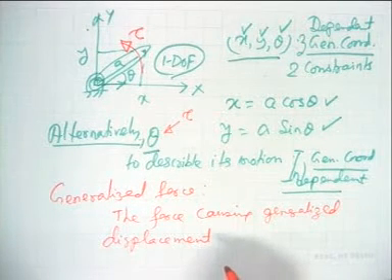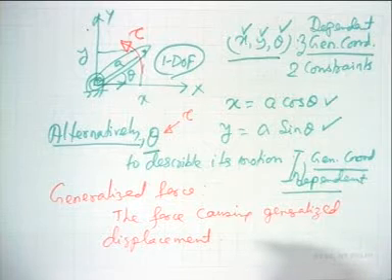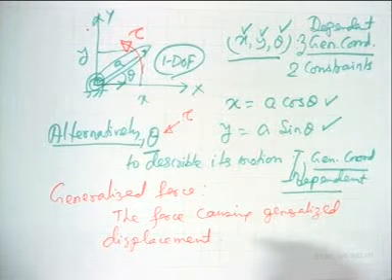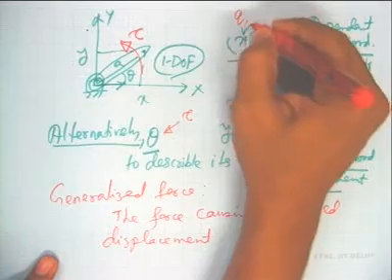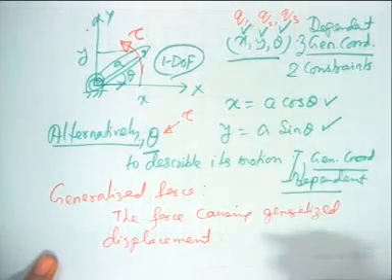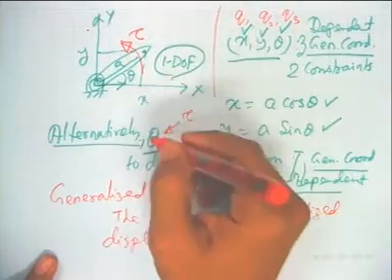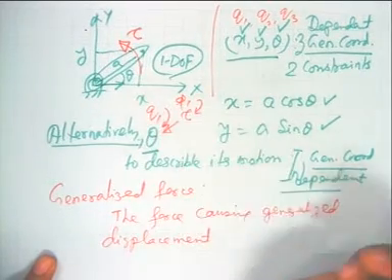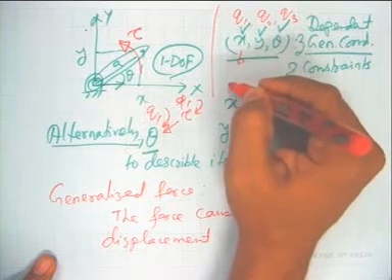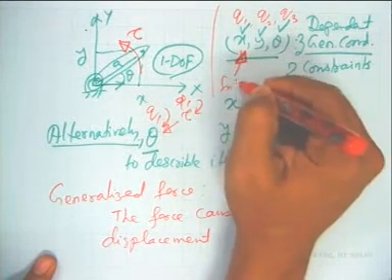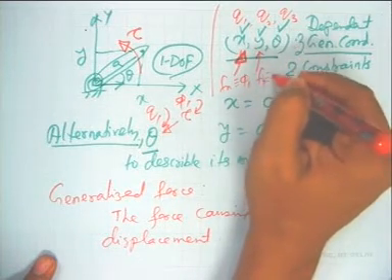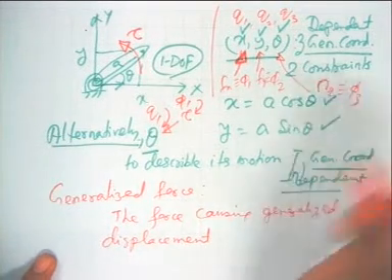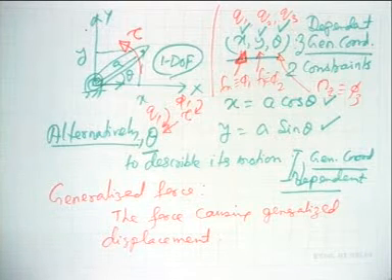Okay. So, in the Euler-Lagrange equations which you have seen on the screen, that is d/dt of del L by del q_i dot, minus del L by del q_i, is equal to phi_i. So, according to that notation, this could be q1, this could be q2, this could be q3, and this is one set. In an alternative way, this is just q1 and this will be phi 1. For this one, if we want to define the corresponding force which will cause it, maybe Fx is equivalent to phi 1, Fy is equivalent to phi 2, and this one is equivalent to say Nz, equivalent to phi 3.